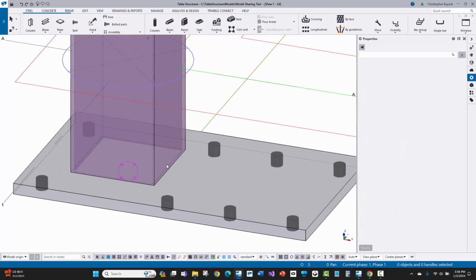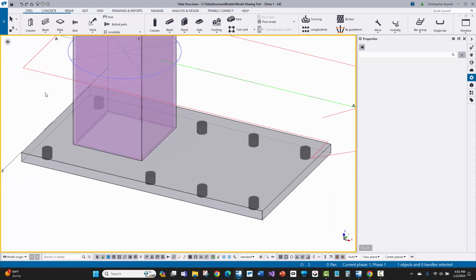They actually want to do partial welds on each face or each side. So I'm going to go ahead and show that next. Now, in this particular case, we're going to use polygon welds and we're going to only do a straight weld on each side of the column, rather than trying to do an all the way around, including the radiuses at the corner of the column.